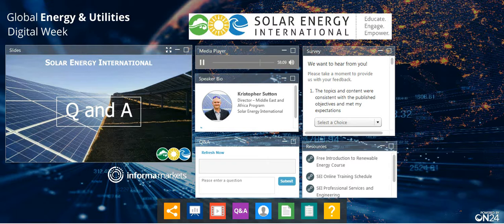There's kind of two reasons why we want to shut that inverter off. One, without a battery, it's not a very good backup system because we would be subject to the size of the solar and the loads and all that. And two, whenever the utility grid goes down, we don't want to push electricity into a dead line, for service and maintenance and safety purposes as well. So if we need backup power when the grid goes off, then we need a battery-based system.